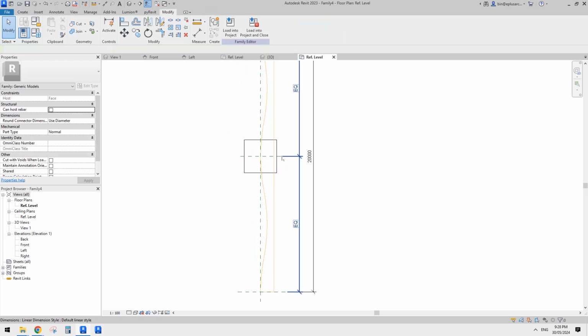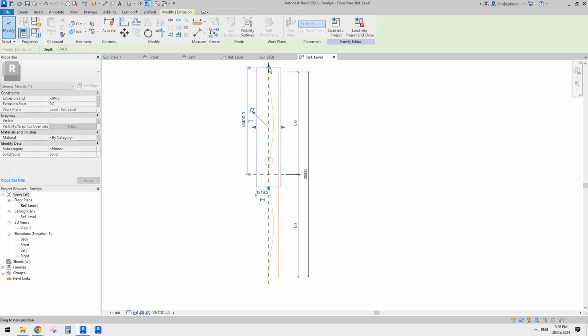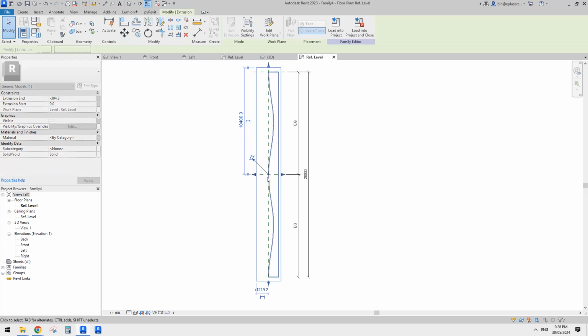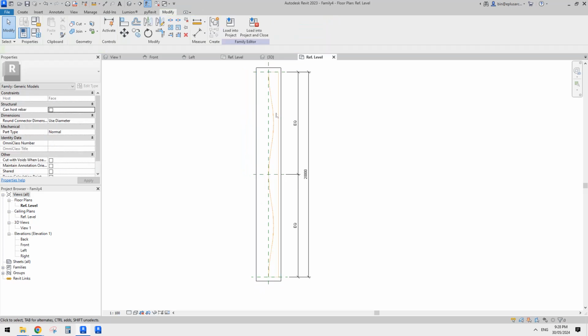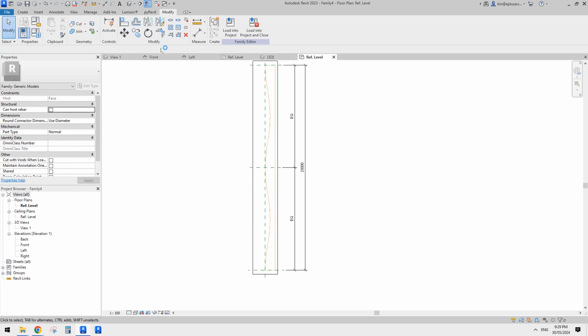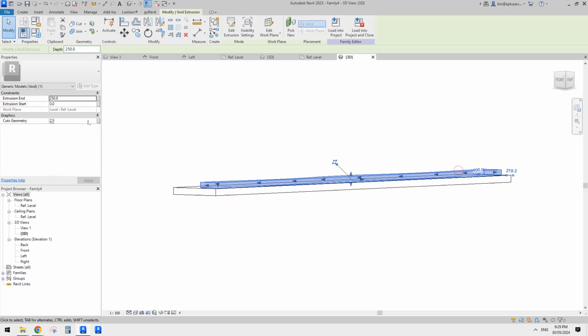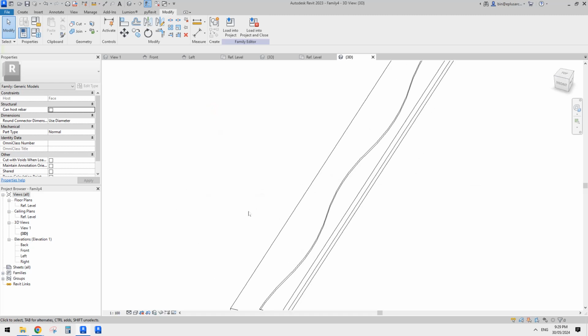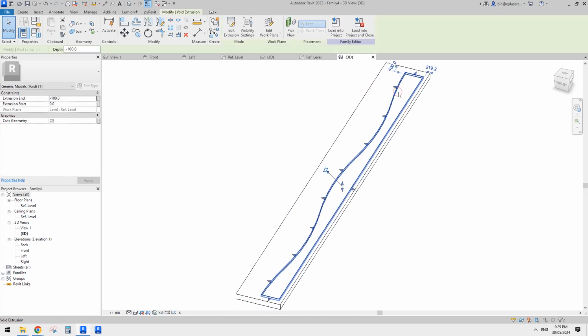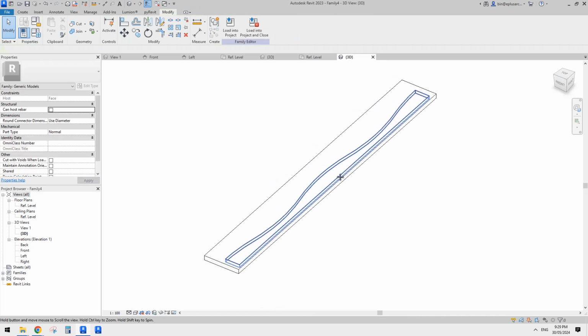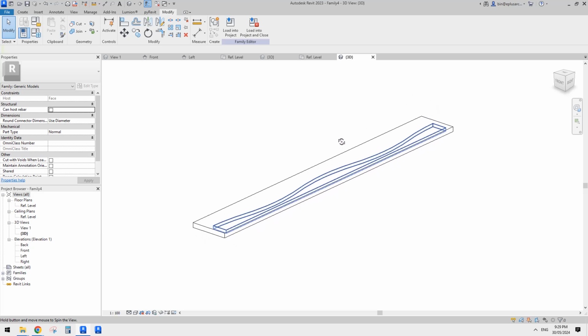Okay, and I think we might need to drag this base, so we can cut the base with this void. Oh, it's not working. Let's have a look at what's going on here. Okay, need to go down, right? So instead of go up, I'll type negative. I think 100 is enough because our panel is 100. Unless you're going to create thicker, maybe I'll just make it 200, in case we need to increase the thickness of those panels.